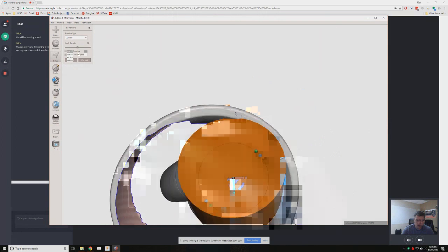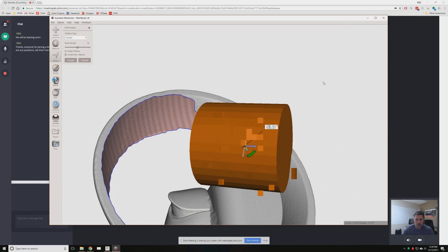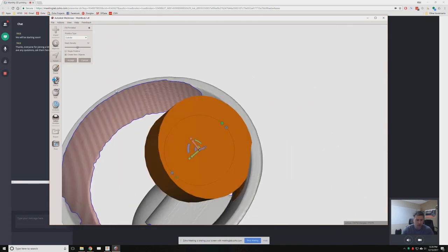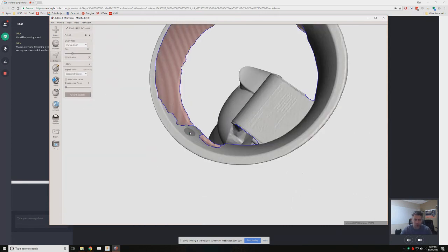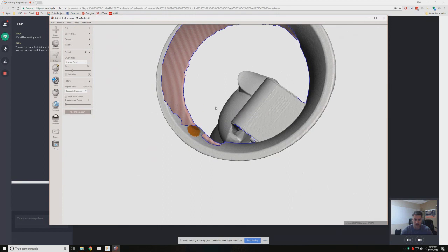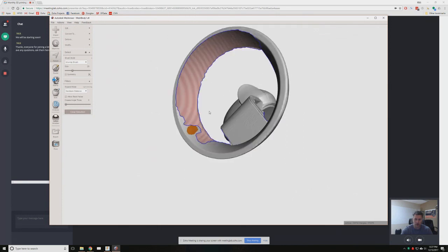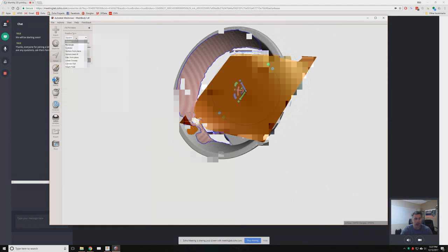That's fine. What I want to try to do is, it's actually going very kind of crazy right now, match the cylinder, or actually a different way of doing this. Let's try to do this in a more intelligent way. So make a selection right here. Make a selection right here. So I have two selections, and let's see what this does with Fit Primitive. And I want to create a single primitive, if you see up here, for a cylinder.